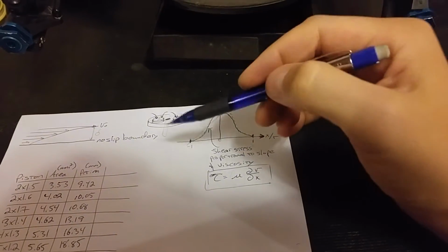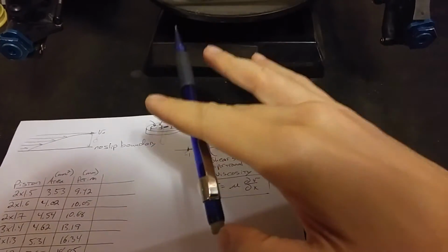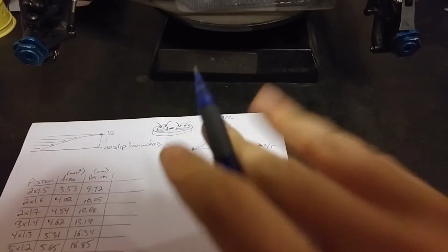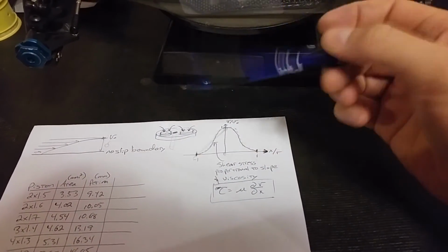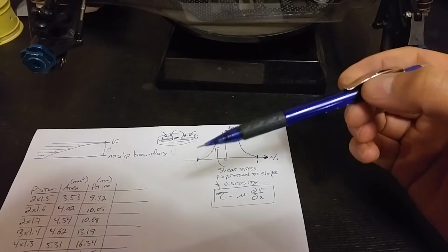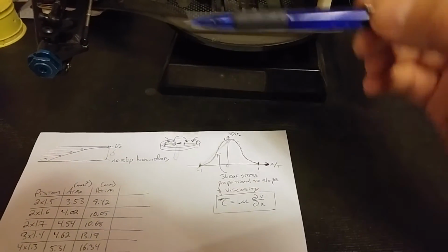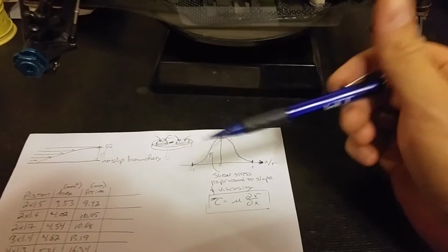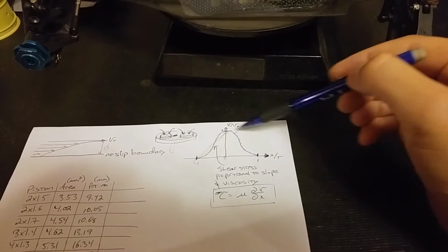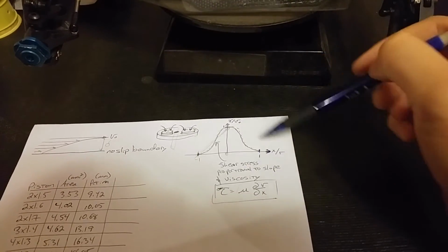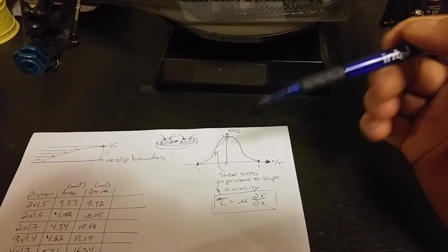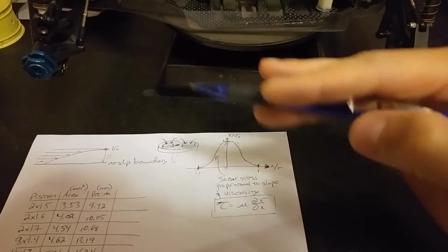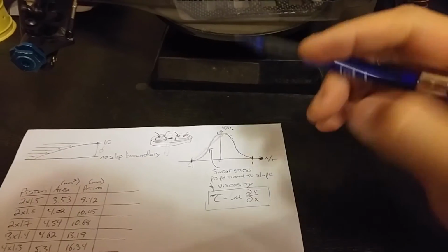And pack happens when you're landing off of a jump, or if the car is driving on a bumpy surface and there's a lot of high frequency inputs into the shock that try to push the shock piston up very quickly. This causes this shear stress condition to happen, and it results in an increase in resistance of the shock damping action.